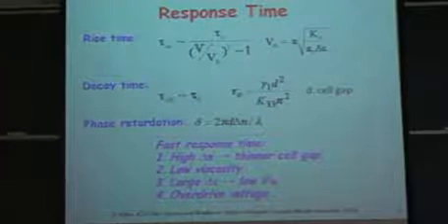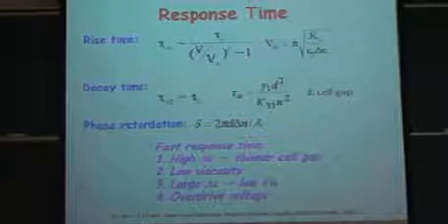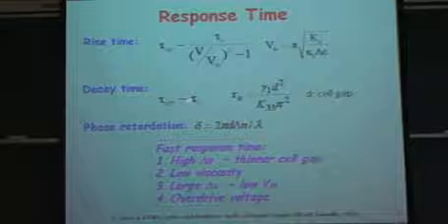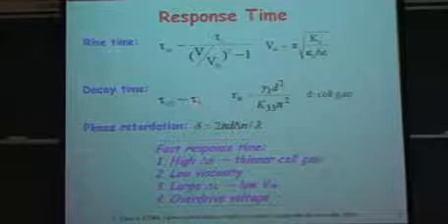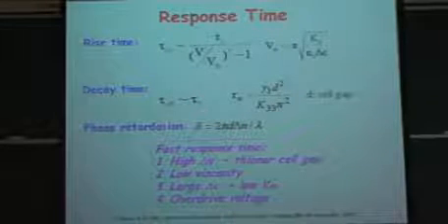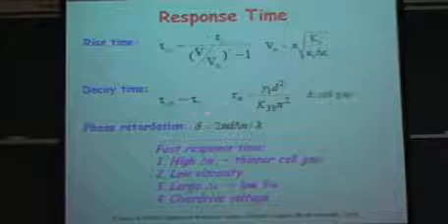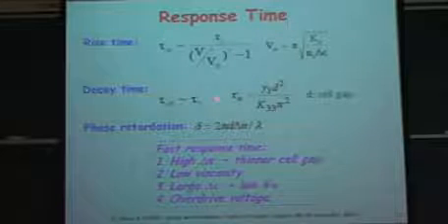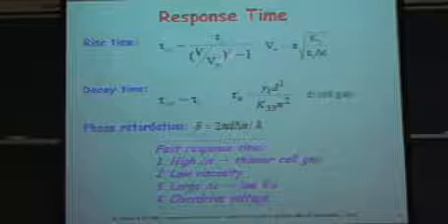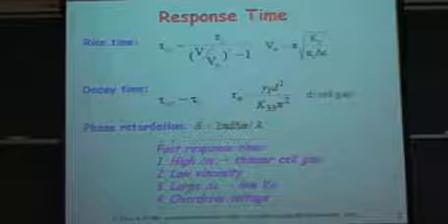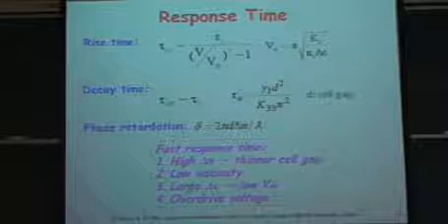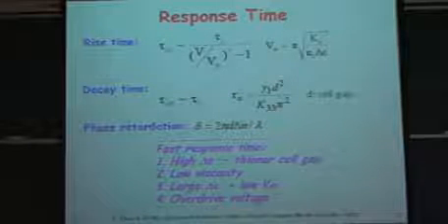So for all liquid crystals, we can get a faster rise time. But for dual frequency liquid crystals, because we can use high frequency voltage driving, for the decay time we can also have such a factor. So both rise time and decay time can be assisted by voltage.